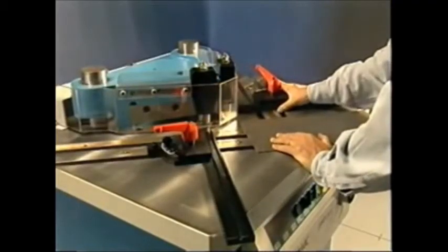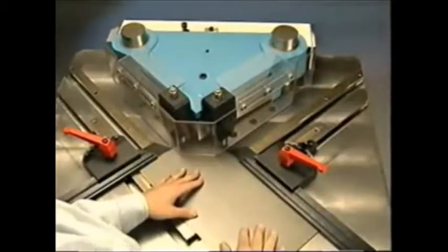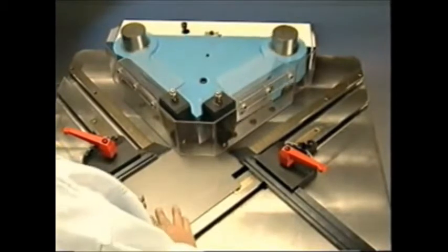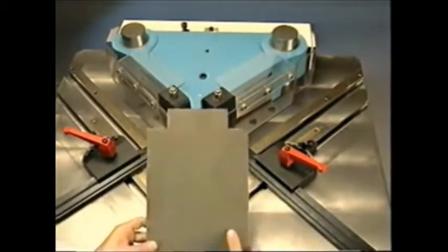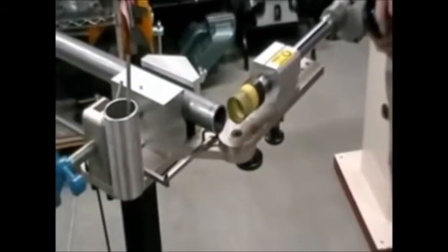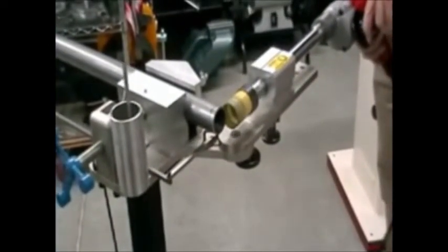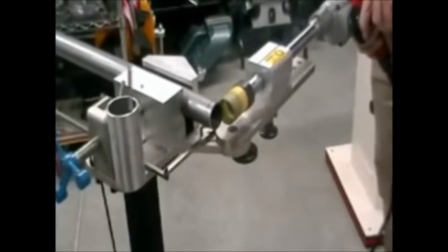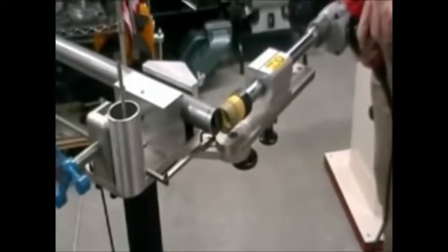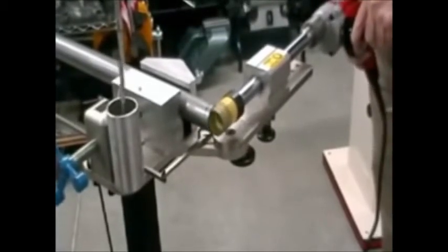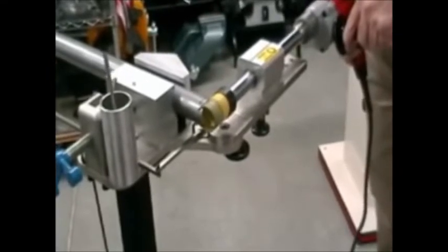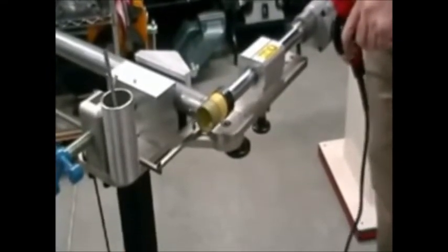The next cutting operation is notching. Notching is when a progressive die is used to cut the outside of a sheet metal to create a specific strip profile. Tube notching is one of the most common types of notching operations. It is implemented to create a T or similar joint between tubes. For example, tube notching is used in building bicycle frames where there are many angled tubes. Each one has to be notched so that all of them fit the design perfectly.